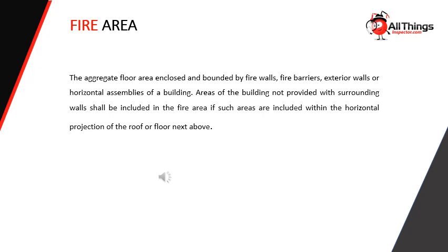Fire area, the aggregate floor area enclosed and bounded by fire walls, fire barriers, exterior walls, or horizontal assemblies of a building. Areas of the building not provided with surrounding walls shall be included in the fire area if such areas are included within the horizontal projection of the roof or floor next above.